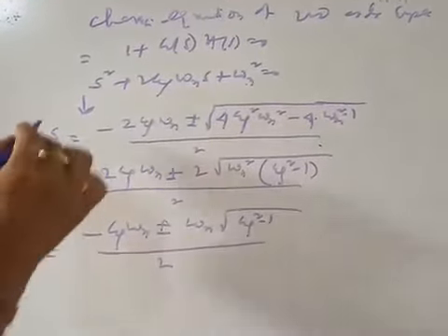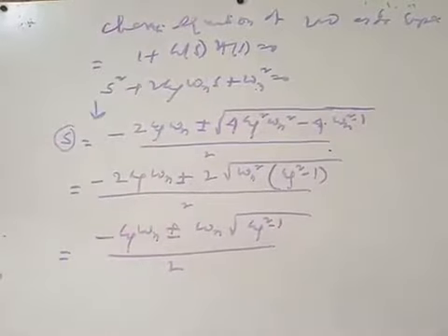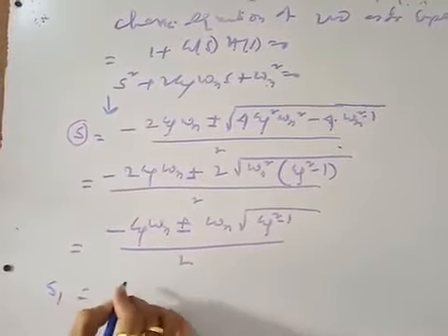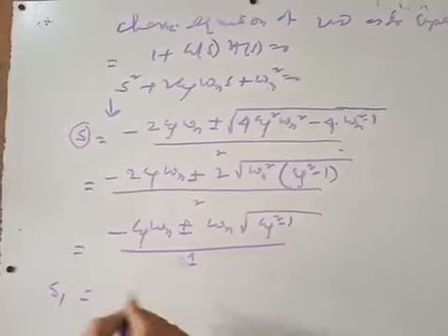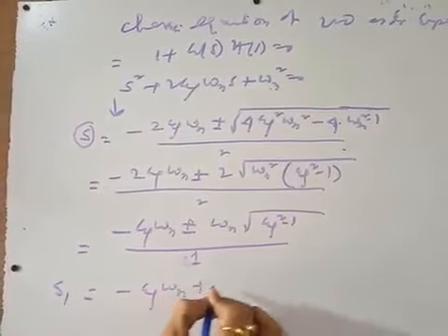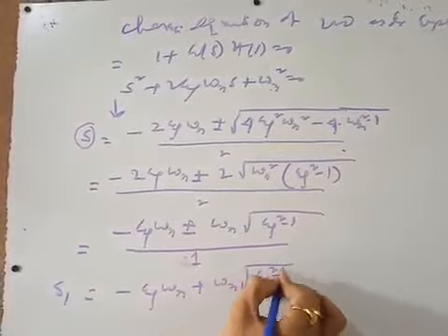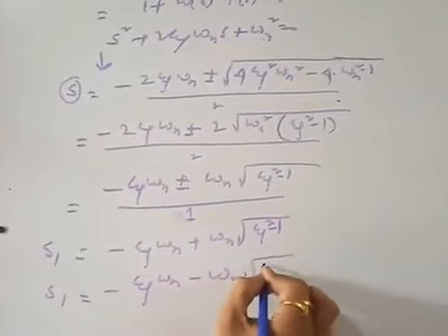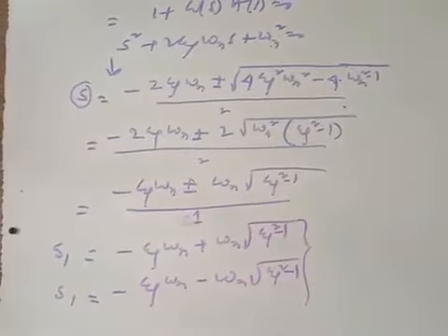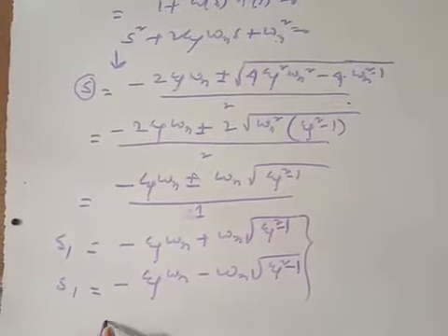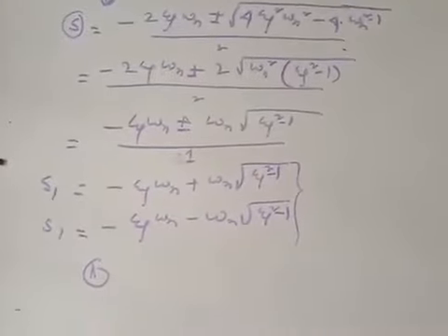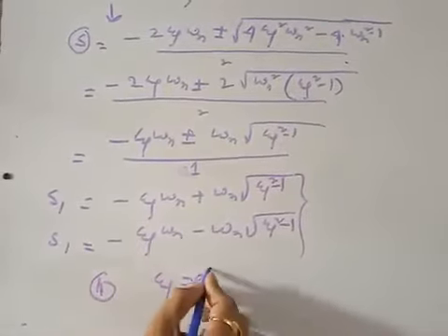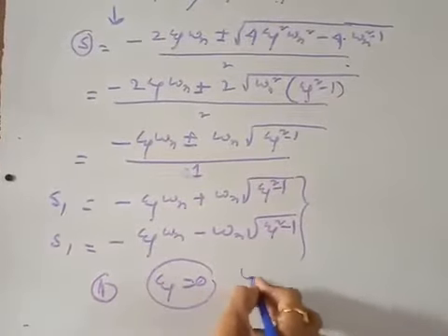See the two pole locations, as this is a second order system, so definitely we will be having two poles. So what are the two poles? Say s1 is equal to minus xi omega n plus omega n root over xi square minus 1, and s2 equal to minus xi omega n minus omega n root over xi square minus 1. These are the two pole locations, right? Now what happens? The defined conditions we will have to take, right? See, first case we will consider the value of xi is equal to 0. That means undamped.